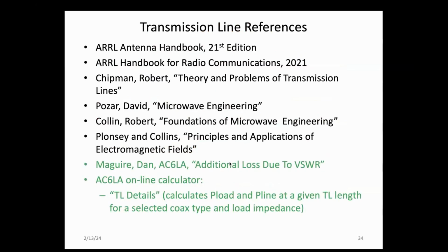Just wanted you to know that there is an online calculator by AC6LA. It's called TL Details. You input a number of parameters, including your selection of coax, your frequency, the load that is terminating the line, and it will calculate both the load power and the power lost in the line. And that's it. Thank you.